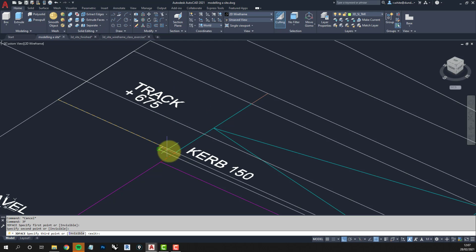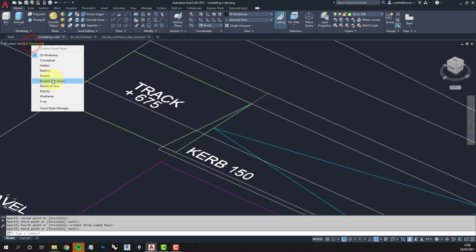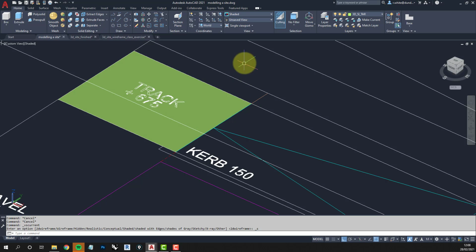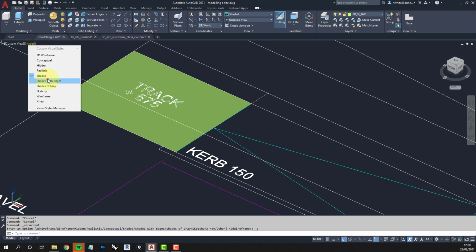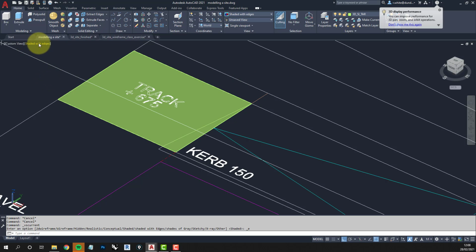Okay, now what I'm going to do here is give myself a bit of a chance for working in other shapes later on. So I'm not going to do a full rectangle there. I'm going to go to this point and then over to here. Okay, and I'm going to put this bit in as a separate smaller triangle. So it's a 3D face again. Okay, so these lines won't be visible when things render up. If I do it as just shaded, we don't see the joint, but if I did shaded with edges, you do see that line.